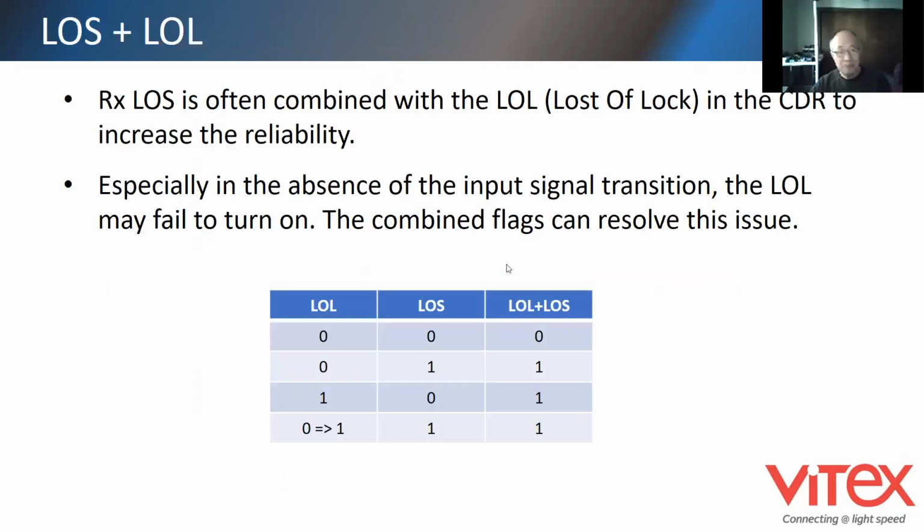So the other point here is how you gang up the LOL with LOS. To improve the reliability, there is one case I want to tell you where it is a must to gang LOL with LOS. In the absence of input signal transition, right? When there is no transition in the input power, the LOL, the loss of lock, may fail to turn on even though the CDR's frequency is drifting off.